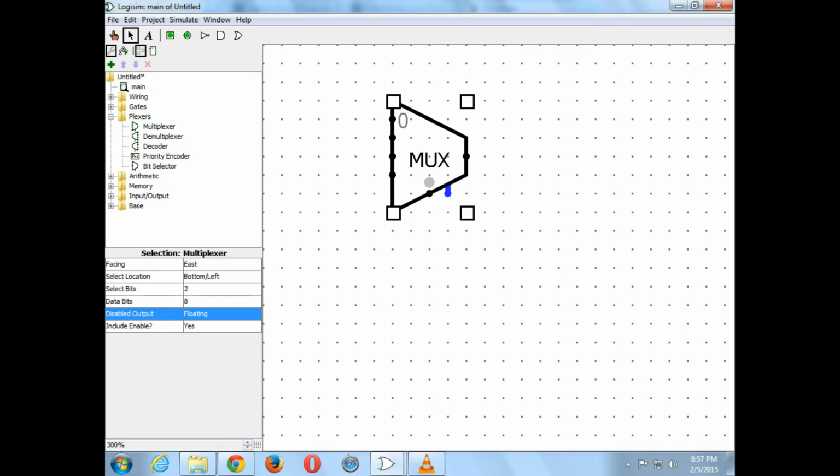So floating also means it's not grounded, right? Floating means it's not connected at all to the high or the low rail. So it's the two open. Exactly. Both switches are open. You're not connecting it to VCC. You're not connecting it to the ground signal. So no one is specifying. This component is not.